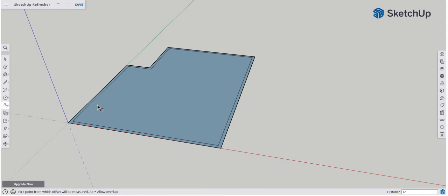I'm going to create some little rooms in here, and this is going to be a very awkward floor plan. It's not going to be with all the thought that you guys put into your 2-bedroom apartments. This is just a practice of basic skills, just to get you guys back in the groove. I'm going to tap R, which gives me the rectangle tool. I'm going to go from this endpoint here and drag into the center, and I'm going to do 12 feet by 12 feet.